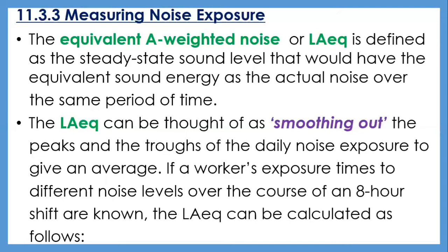The equivalent A-weighted noise level, or LAEQ, is defined as the steady state sound level that would have the equivalent sound energy as the actual noise over the same period of time. The LAEQ can be thought of as smoothing out the peaks and the troughs of the daily noise exposure to give an average.